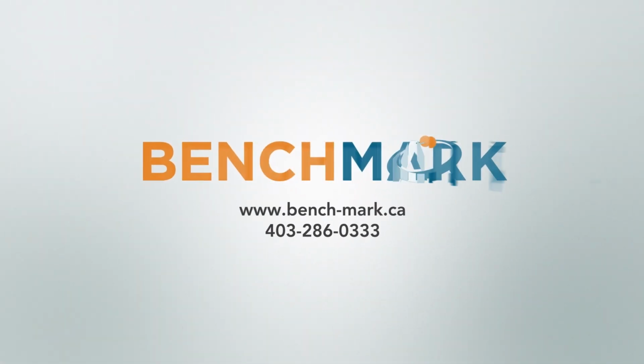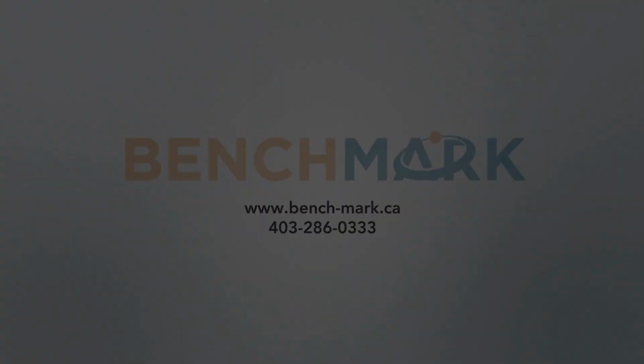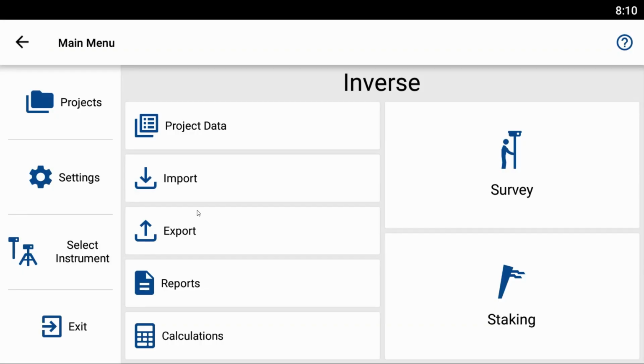Hi, this is Nolan from Benchmark, and in today's video I'm going to be showing you how to perform an inverse measurement with Microsurvey's FieldGenius for Android. So what an inverse allows you to do is see the distance and bearing between a set of 2 points.